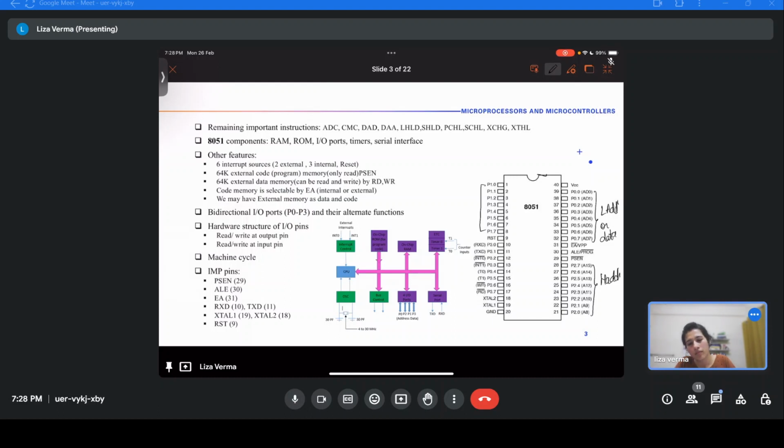Reset will do what? Upon reset, what are the values of all the main registers? I think everyone knows everything goes to zero, program counter goes to zero. What is different is the value of the stack pointer, right? So where does the stack pointer point to after reset?